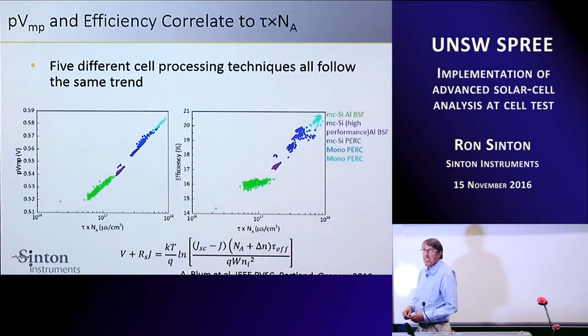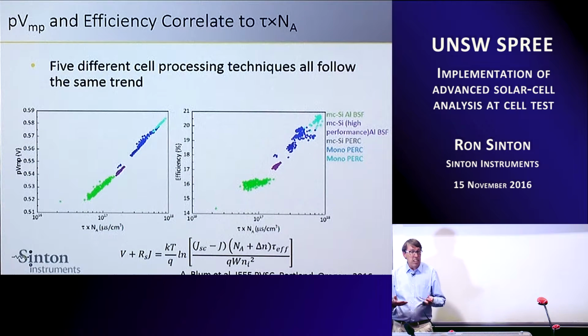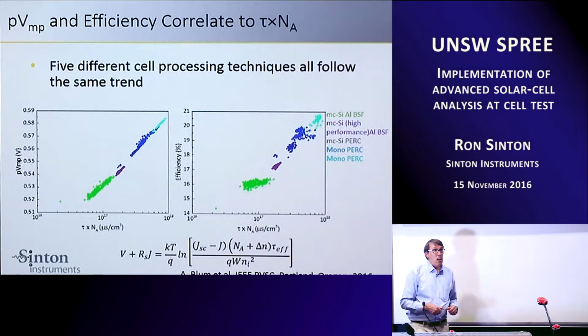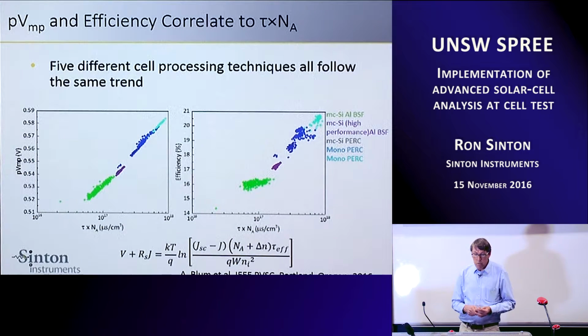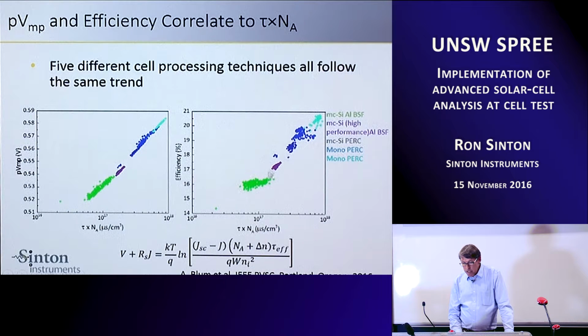And the reason for this is that efficiency isn't only voltage. It also has current dependence and series resistance dependence, which, because we have different vendors and different technologies and different cell designs, is much more scattered. So this is a good place to get your fundamental parameters here.